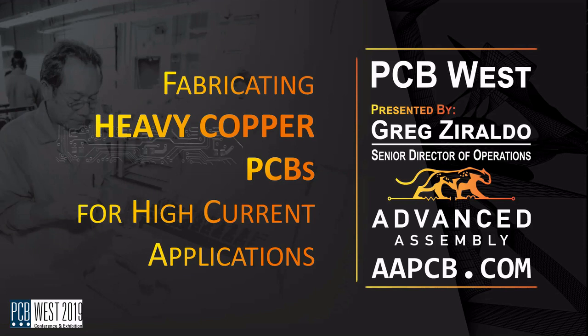Ultimately, typically in heavy copper, there's going to be a separate drill for the vias and the actual plated through holes, so there are different plating steps and different imaging steps. The more of those steps you can reduce, the more it's ultimately going to be a cost savings. Unfortunately, cost savings and heavy copper are kind of the antithesis of each other.